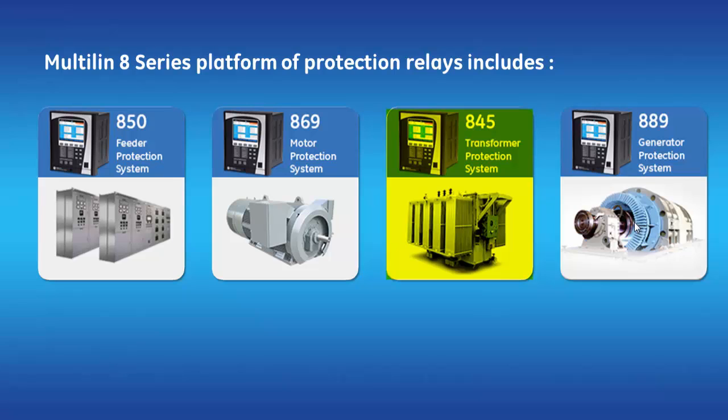845 is also integrated with DGA devices, for example Transfix, which can analyze 9 types of gas produced when a fault occurs. So when combined with the 8 series relay protection elements and event recorder, the user has a better understanding of the fault gases associated with the fault types. 889 is a generator protection relay used for medium and large generators.